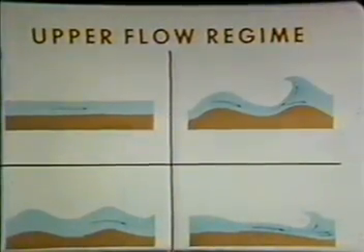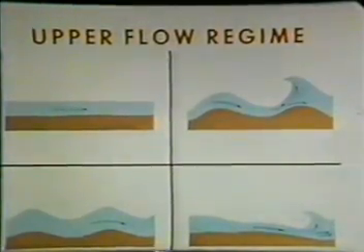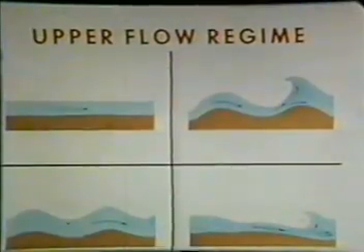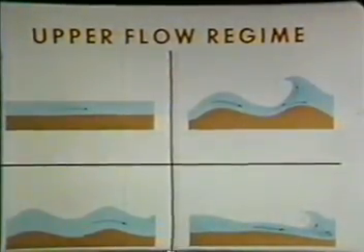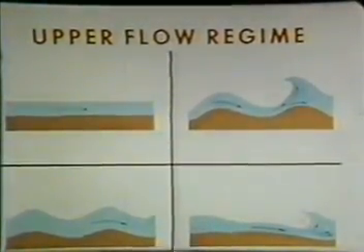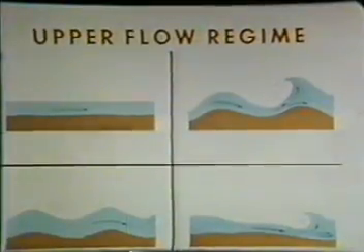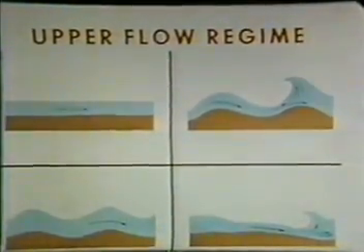In this flow regime, the water and sand waves are in phase, just as for rapid flow with a rigid boundary. Sediment transport is large, 1,500 to 60,000 parts per million or more, and resistance to flow is small. Manning n will vary from 0.012 to 0.018, and Chezy C from 50 to 120.